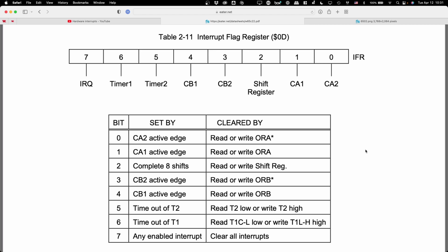So this is how you prevent the situation in his very first video on interrupts, where when you hit the button, the counter actually goes up by hundreds. Because it was basically interrupt, clear, dealing with it over and over again, because no matter how fast you press the button, you're not pressing it at 1 megahertz, right? Okay, so does that kind of make sense, sort of?